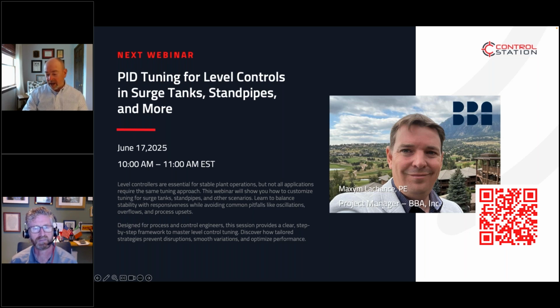Yeah, the one added advantage of the modern smart positioners is not only do you get a little more ability to tweak and adjust, but you also get more information being captured that can be further analyzed later. That's the big improvement there in terms of whether it actually improves Stiction or not. Again, this is going to depend a lot on the specifics of that issue. A lot of those vendors now have edge IO, so you're bringing a lot more information back from those controllers across their own networks, to be able to make good decisions and good maintenance actions from it.